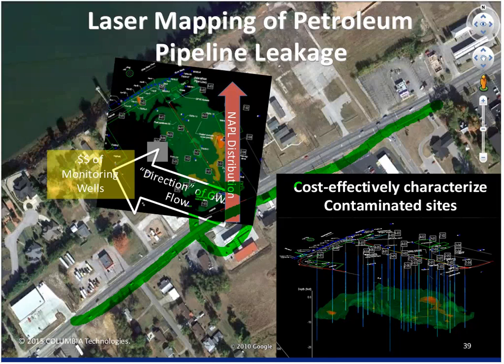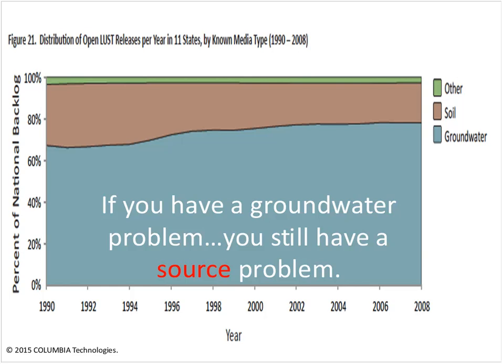In this situation, the pipeline rupture was much more shallow than groundwater. The distribution of the NAPL was through the pore spaces that were unimpeded by groundwater. So the LNAPL went north and the groundwater table went left. Once it reaches equilibrium, then the situation will change. But in the early points of a release, groundwater is not going to be the primary contributor to the direction of the LNAPL release. So groundwater is important, but it's not the answer, I guess, is the bottom line there.